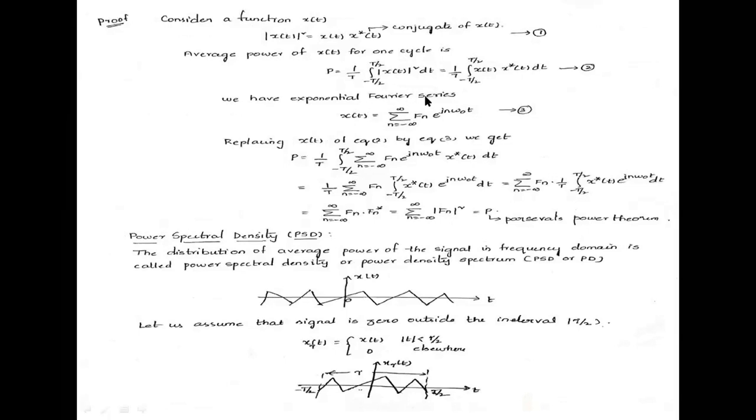The Parseval's theorem for the power signal. Here we are applying the Fourier series. So there, energy spectral density was used to find the energy signal; for Parseval's theorem here, we are using the Fourier transformation. This we already discussed. The squared magnitude is x of t and x star of t, the conjugate function. Substitute the squared magnitude as x of t and x star of t.